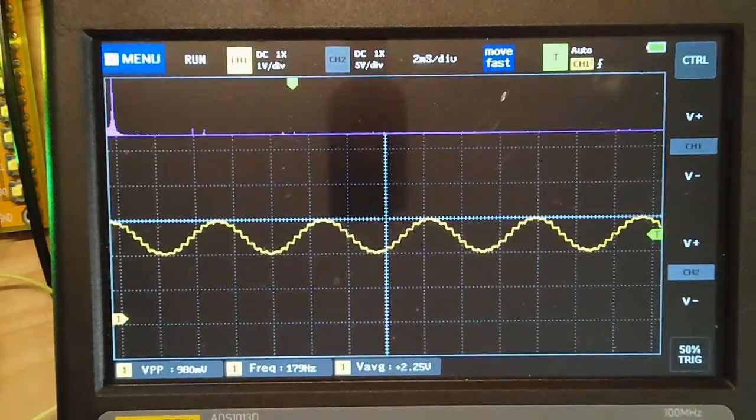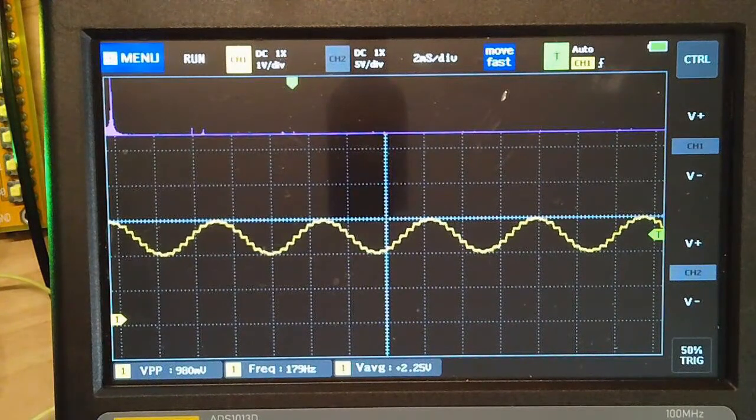So what you see is this. This is the frequency response of a sine wave. It's got the first harmonic, that's your sine wave, plus there's a bunch of higher frequencies up here. This isn't a pure sine wave, you can tell by the squares, these stair steps, but it's pretty darn close. With a little bit of filtering, I can get rid of these high frequency harmonics and get a sine wave.